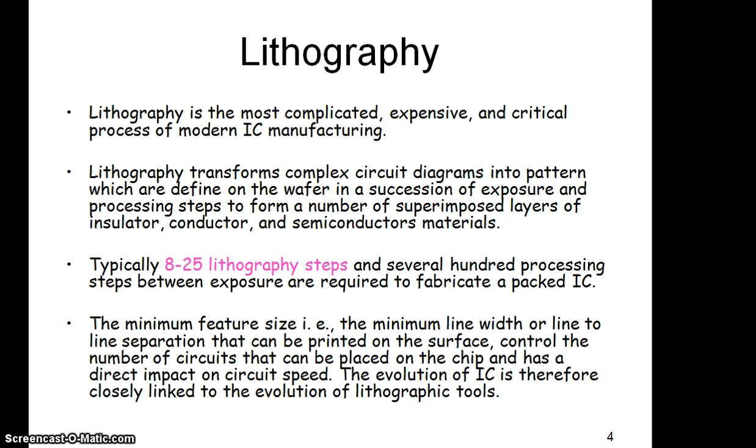So basically lithography is a technique to transfer the pattern from the mask to the actual wafer, or silicon or any other substrate which you are going to use for your device. Lithography is the most complicated, expensive and critical process of modern IC manufacturing.